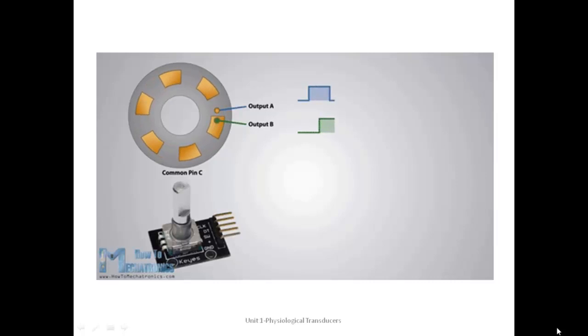In this diagram, you can see as the disk is rotating, the blue and green colored pulses are being generated. See over here, the two were insulating, blue gets touched first. So the blue wave is actually leading the green wave. Because the blue one, see now, this corresponds to 0. Now this corresponds to a high. Again it corresponds to 0. Again now it corresponds to a high because it touches the conducting area. Okay, so likewise we can measure the rotation that is taking place.